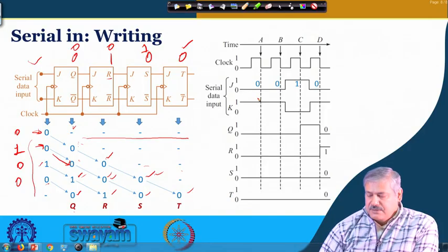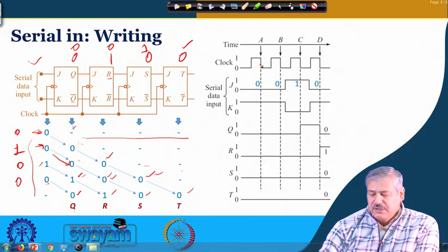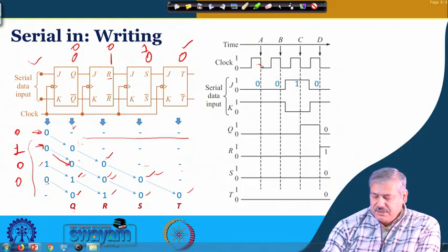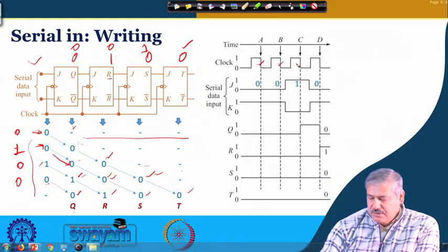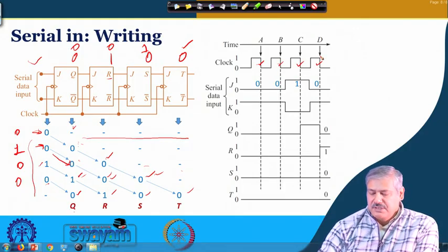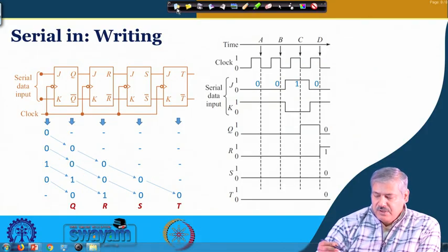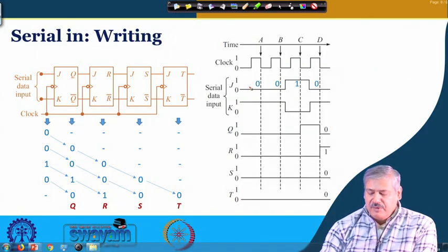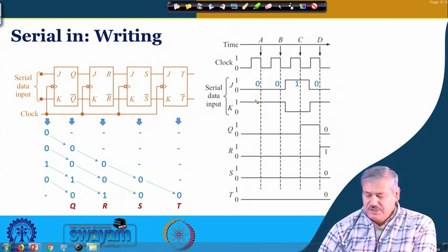And the example is given through the timing diagram, right. So, what is of importance here is the clock edge, right. So, it is negative edge triggered, that you can see, this is the negative edge, okay, at which it triggers. So, at that time whatever is the value that is present for J, here it is 0.